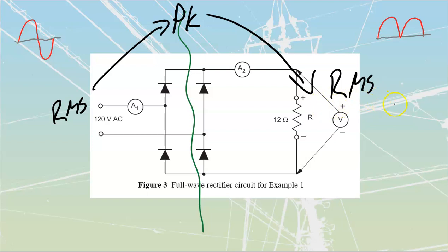Once I know my total amount of power on this side, I would know my total amount of power that I would be delivering on this side over here, which would mean that I could then figure out my VA in, VA out, all the rest of that stuff. Those same rules, the amount of power that's going to be dissipated by a circuit has to be supplied by a circuit, are the exact same as on a transformer. They're not as formalized, but we get that. The amount of power supplied by our source has to be the same as that dissipated by our loads.